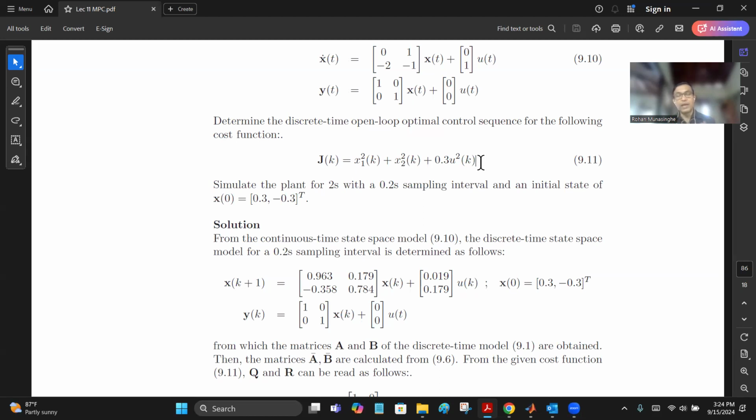So you keep those as is without any discount or amplification, but the control effort you square and discount, taking only a 0.3 portion of that. So the cost functions are context dependent. If you are given one, you can use it, or if you want to find it out, do a reasonable assessment and find out what the cost is.